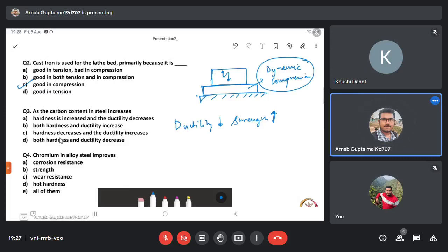So along that plane, if you put some interstitial carbon and you keep on adding that carbon, then what will happen? This interstitial carbon will arrest this gliding motion. It won't allow this slip to occur smoothly, and thereby it resists the deformation process. Hence, we can say that the strength of the material has increased. But at the same time, as we know, its ductility will also reduce.